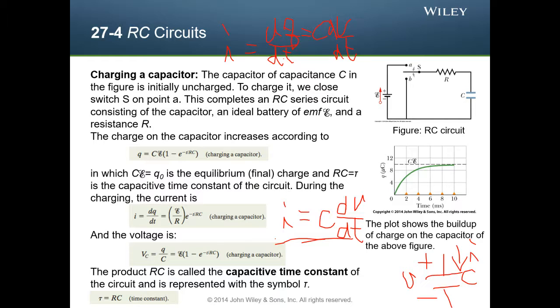But the special case is if a equals minus 1 over RC, then V(t) should be something like this. If this one repeats with the homogeneous solution, you need to multiply a t on the particular solution. And actually, when you learn how to solve the differential equation, you need to remember all these rules so that you can get the correct solution.